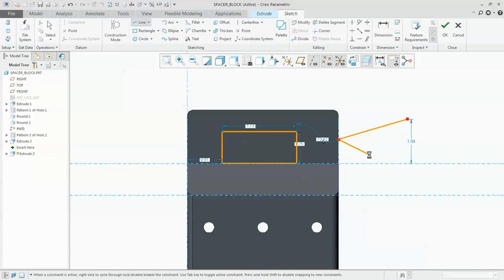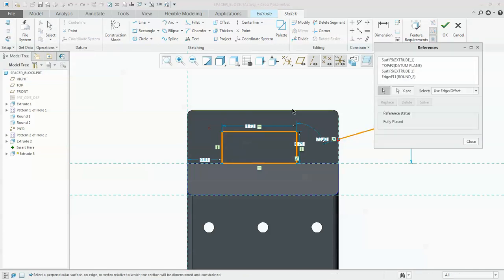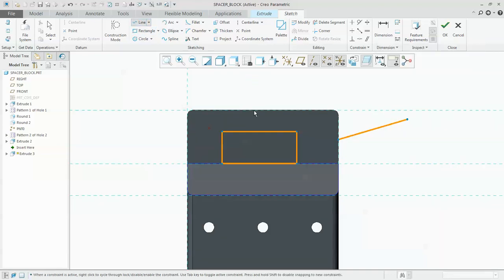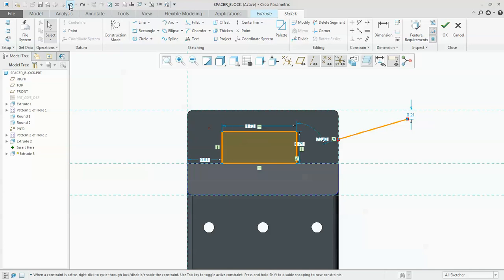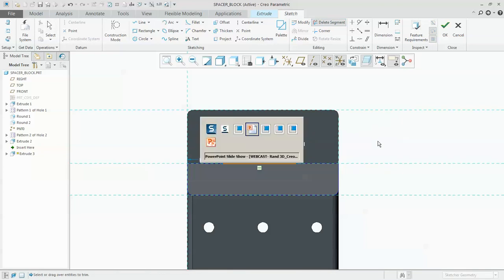I'm going to come out of that particular feature and just hover over the line there, and you can see that it's a sketch reference without me having to go into the references tool there from the setup group and outright mark a reference and then come in and start sketching structure in order to snap to it. I could, as I'm creating the geometry, have that snap happen while I'm in the process of creating, which can be very handy if you find that that benefits you. It's there now. Let me delete this piece of line segment right here and go back to our information because there's quite a bit.